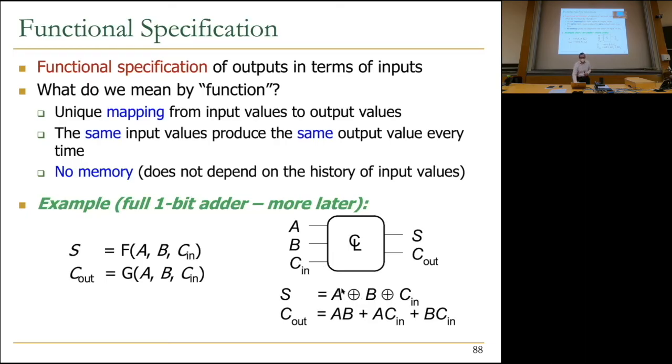It's really an XOR function, as you can see. It's the XOR of A, B, C. If you don't believe that right now, we'll later draw the truth table, and truth table will show that sum is really the XOR of A, B, C. And C out is the carry out. When you do an addition of two digits, addition of 2 values, you get a carry out for the next addition that you have for the next digit, right? And this is the carry out function.